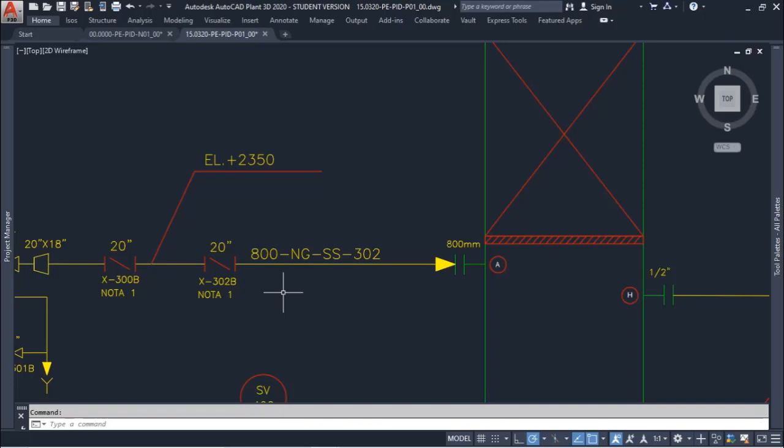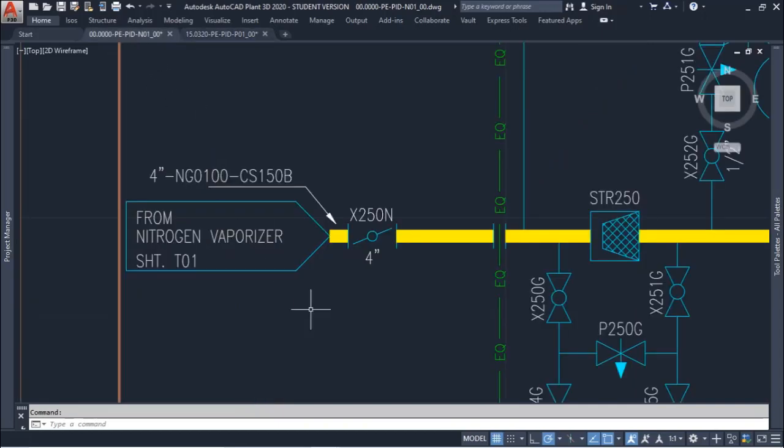And different from the nitrogen compressor P&ID, we have no information about the pressure rating of the piping, and so in this case I am not able to know if this stream is operating around 1 bar, 10 bar, 30 bar or 100 bar, because I have no information about the pressure rating. On the other hand, as I know in the nitrogen compressor system that I have a carbon steel 150, it means that I already have set a maximum allowable working pressure.